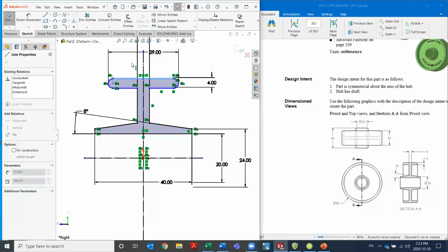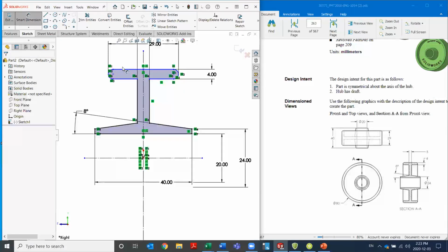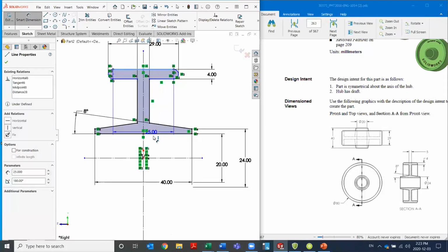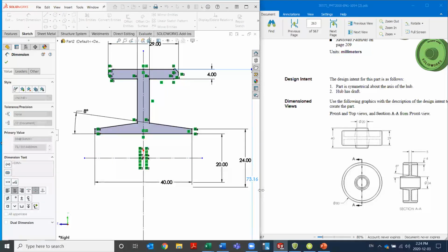I can see, okay, I don't have a distance across here. I've used all my dimensions given here. I've still got a diameter of 80 here, and this is going to give me that overall. So once this has been revolved, that's going to be my distance. So I can add that in and say from this far edge, it's going to be the outside of the wheel here to that axis and cross over, and we'll make that 80.